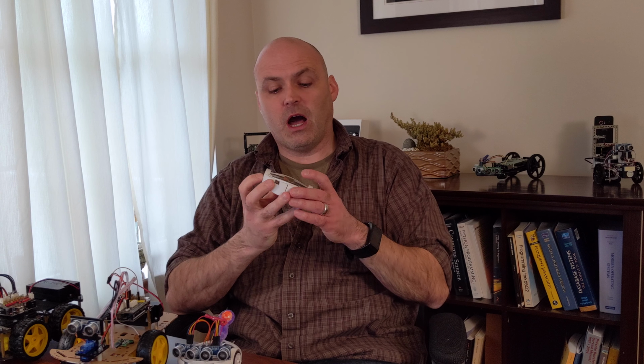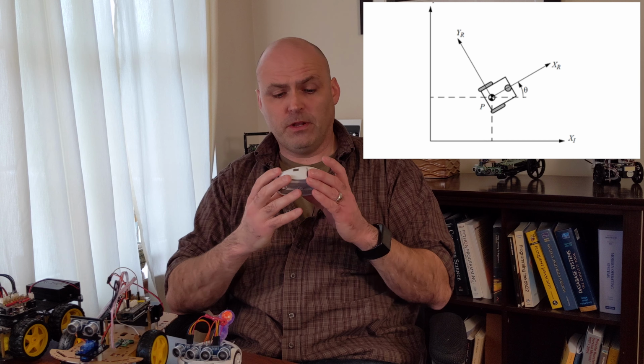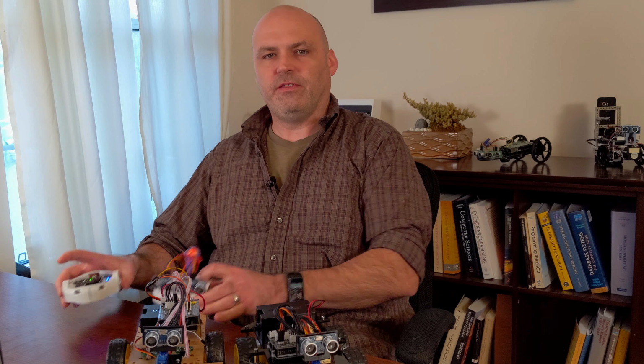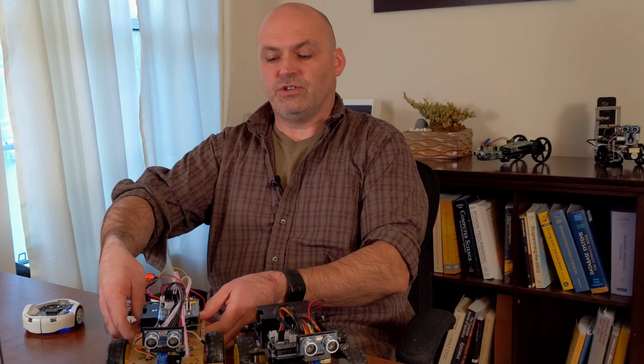Now, there are other sensors that can help us. These have a compass, accelerometer, and gyroscope, and those sensors are very helpful as well because they can tell us things about the inertia of the robot and what direction it's pointing in. So the combination of those sensors is going to allow us to position this robot in space with a fair bit of certainty, although there's going to be some error, and we'll discuss that as we go through. While I'm going to be using these robots in this video series, you can use any differential drive robot.